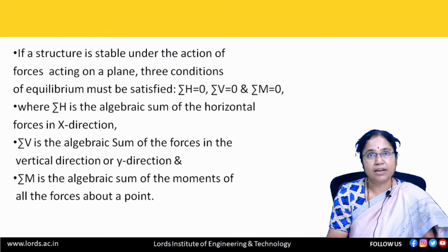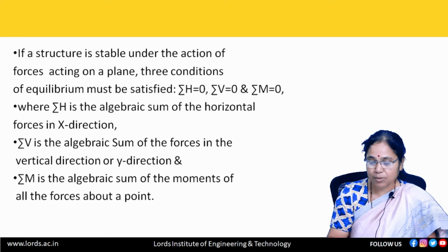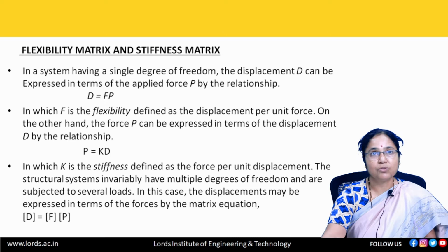be satisfied. They are sigma H equal to 0, sigma V equal to 0 and sigma M equal to 0, where sigma H is the algebraic sum of all the horizontal forces in the x direction and sigma V is the algebraic sum of all the forces in the vertical direction, must be equal to 0, and sigma M is the algebraic sum of the moments of all the forces about a point, must be equal to 0.